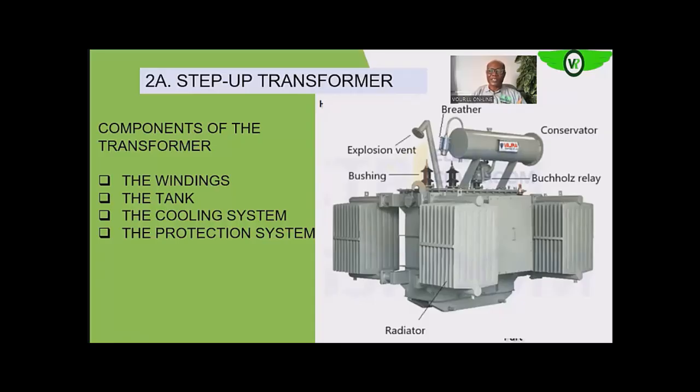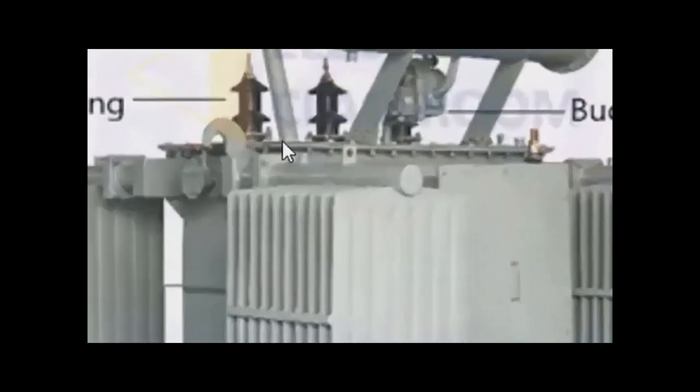Apart from that, changes in the weather condition of the day can also affect the temperature of the oil. So once it is heated, naturally the oil will expand. If the oil that is expanding does not have anywhere to expand to, that can cause overpressurization of the tank, and may either cause explosion or compromise the gaskets between the cover and the tank, and that can cause serious leakage.